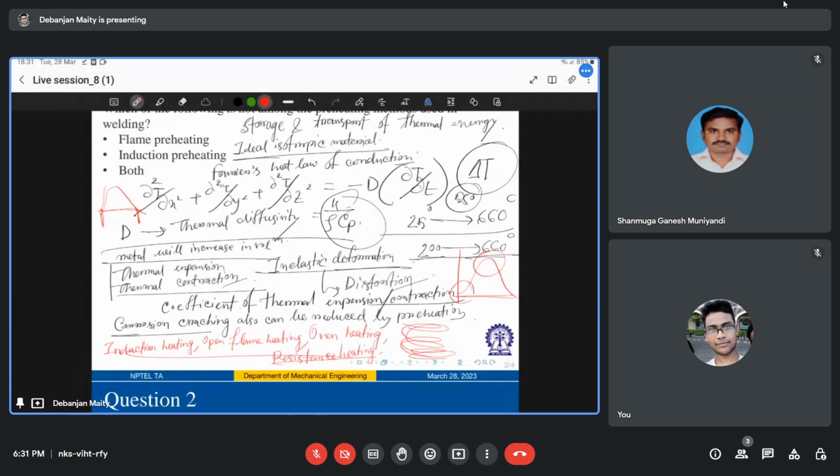So resistance-based heating, how does it work? It uses electrically heated ceramic pads placed on the base metal, and those heated tiles transfer heat to the part through radiant heat or conductive heat where the pads are in contact with the part. Correct.